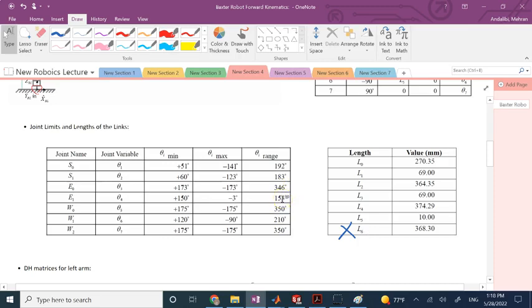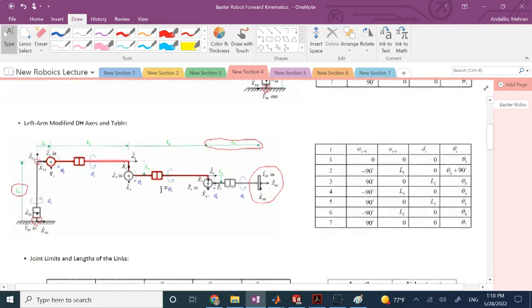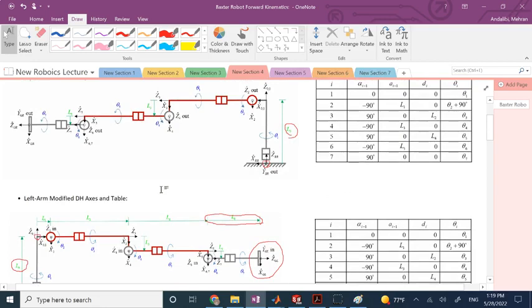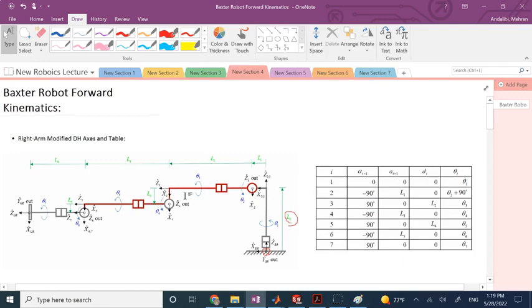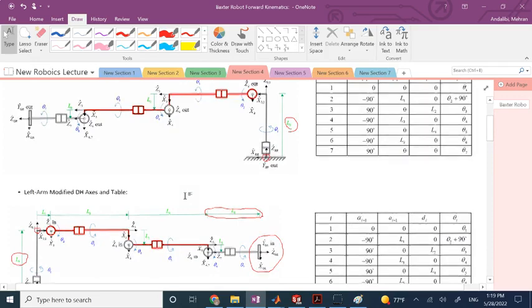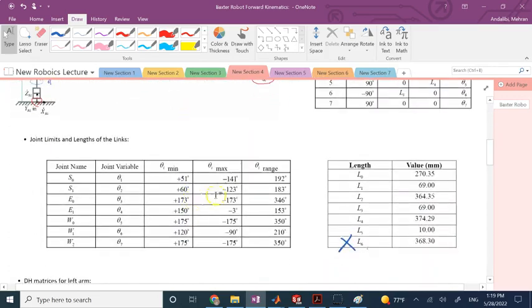But joint 4 can only go a 150-degree range. These are all designed so that the robot's parts do not hit the other links, so they are used basically to avoid collisions. So each joint has some limitations. When you want to do forward kinematics, inverse kinematics, determine the workspace, and so on, you have to keep all of these limitations in mind.